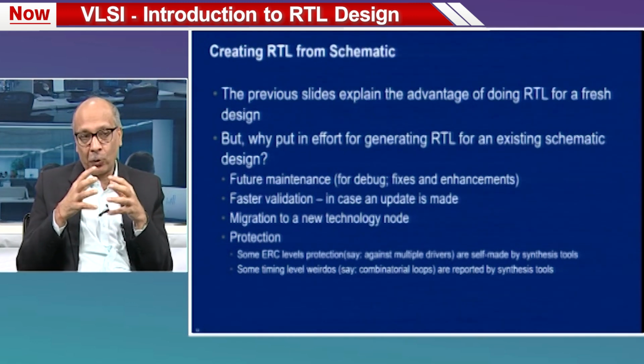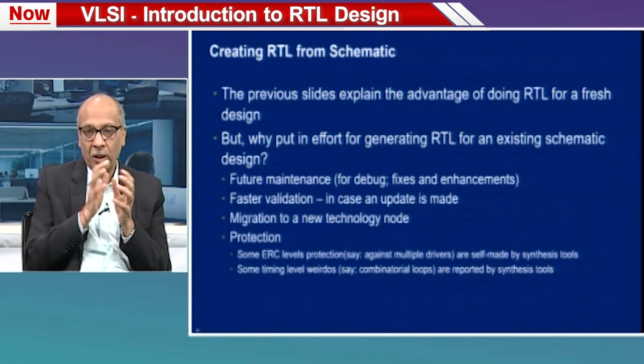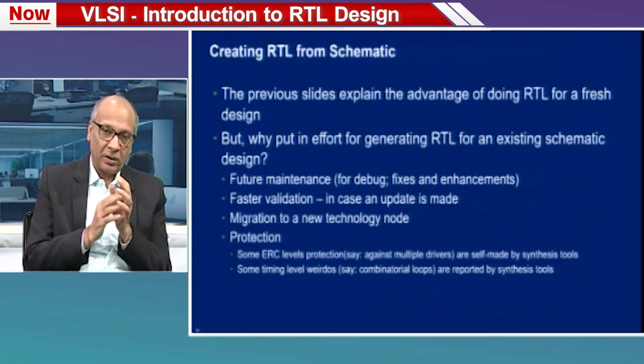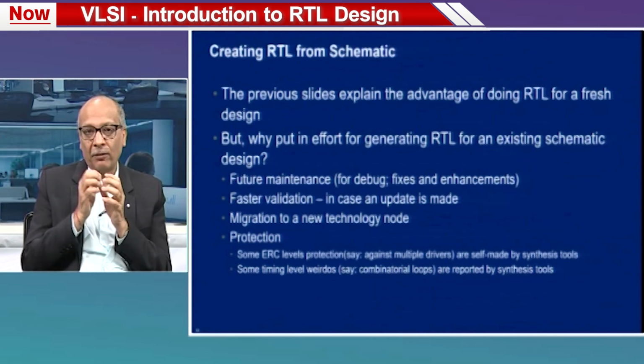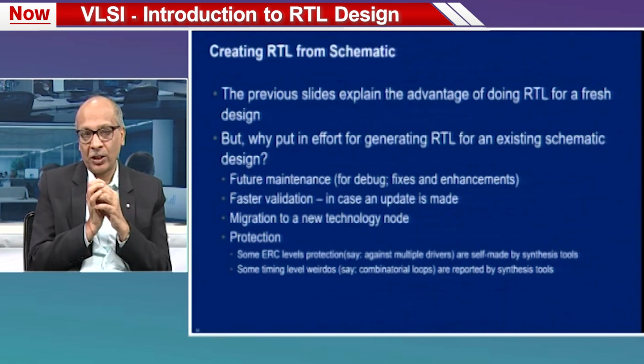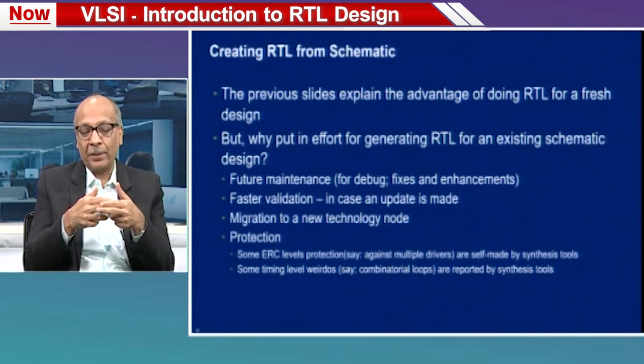And the circuit protection: there are certain things which are totally wrong in an electronic circuit. Synthesis tools will catch and prevent those situations inherently. For example, some electric rule based connections, right? Multiple drivers. You should not have multiple drivers on any given wire. Multiple drivers can result in short circuit, contention, various kinds of things. A synthesis tool will not create a situation of multiple drivers.